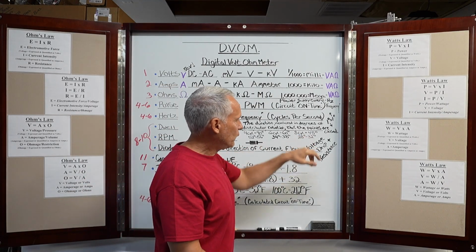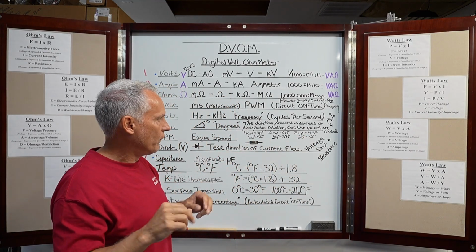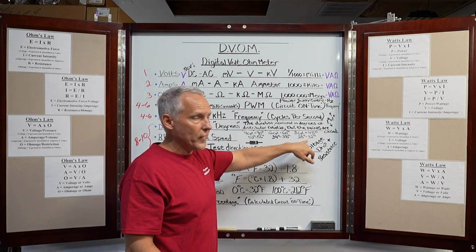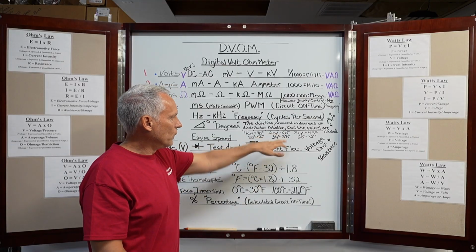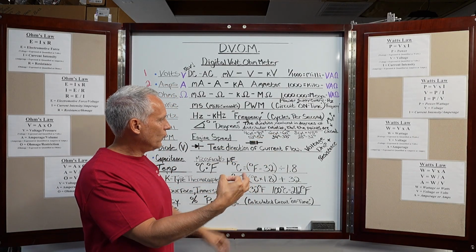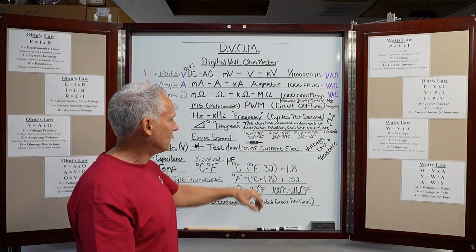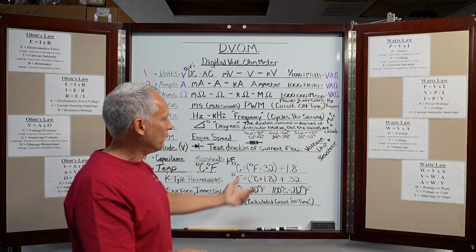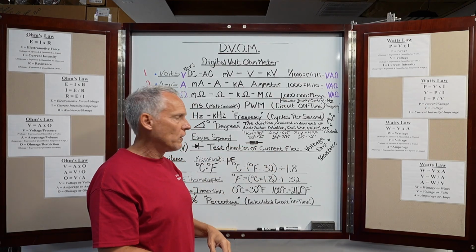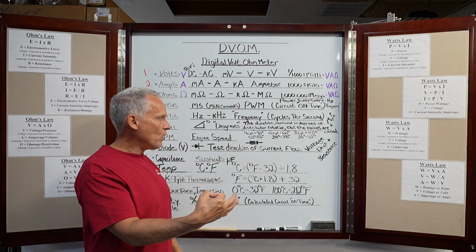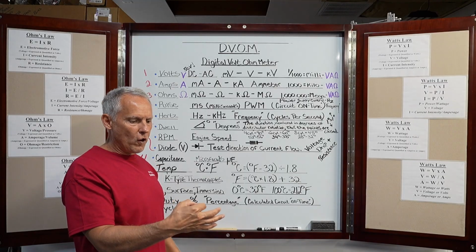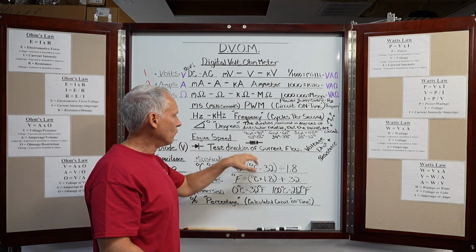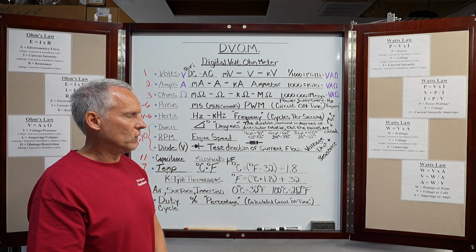So on an 8-cylinder engine, the total available time is 45 degrees. The actual dwell is going to be set between 28 and 32 degrees. On a 6-cylinder, there'll be 6 lobes, so between each lobe 360 degrees divided by 6 is 60 degrees. So basically you have a total potential of 60 degrees. Normally you'll set the points somewhere between 34 and 38 degrees. On a 4-cylinder you only have 4 lobes. Those 4 lobes are going to be 90 degrees apart because it's 360 degrees divided by 4. Dwell is somewhere between 52 and 56 degrees.